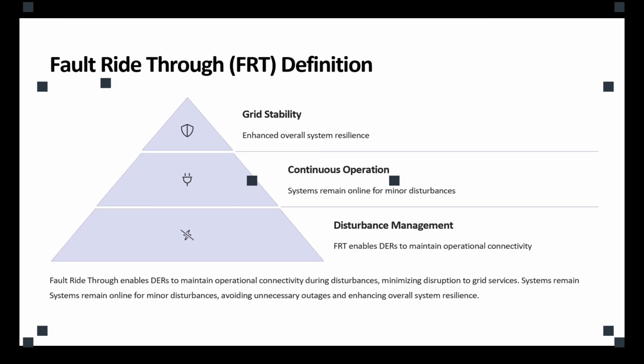We said if we let the protection, which is there to deal with those faults, work ideally, that means every time a fault happens, the instant, because second is not a good unit, we are working on a millisecond scale, the instant that the protection detects that fault, ideally it should break or clear that fault, break down all the connections to that fault, isolate the fault, and save all the other components in our system.